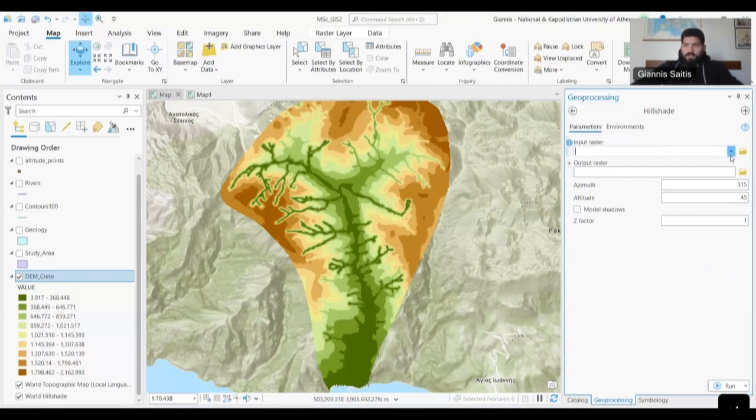And for the hillshade, we're going to use the DEM grid. Okay. Yeah, let's keep it like that. Here we will create a shaded elevation model. Imagine that you have a sun somewhere around, and you set the sun's angle on your own, and the sun will light.